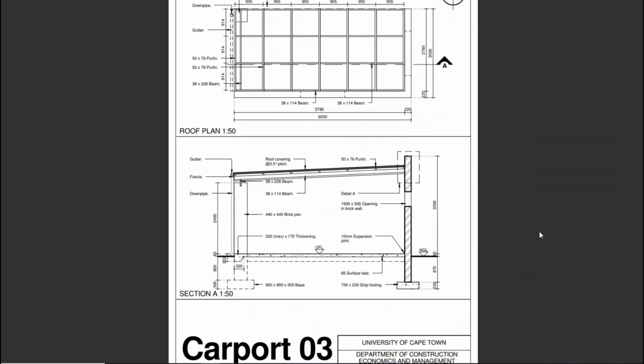So that is the story with a beam roof construction. You've got these layers on top of each other. Just understand what's bonding to what, and apply your connectors, and you will be good to go.